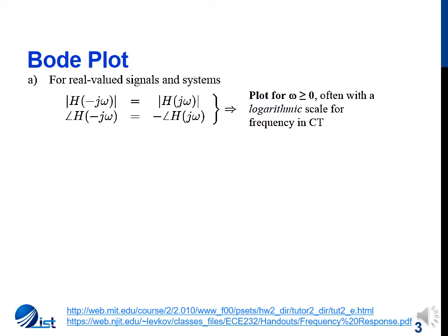Generally for continuous time Fourier transform, that is why Bode plots are used, where the frequency axis is especially logarithmic. In MATLAB or other software you'll see that they also compress the magnitude axis because it's easy to do, and it gives you a better view. So a Bode plot is a technique where you plot the magnitude versus frequency or the phase versus frequency on a logarithmic scale.